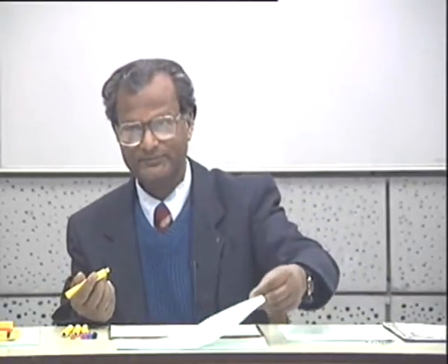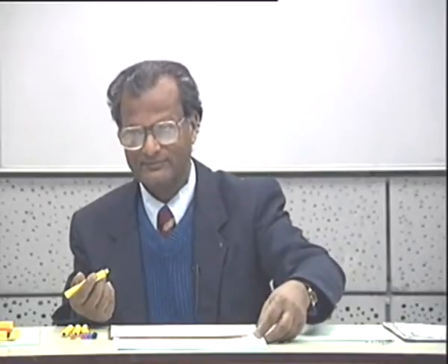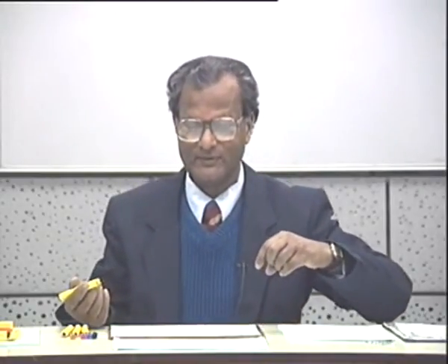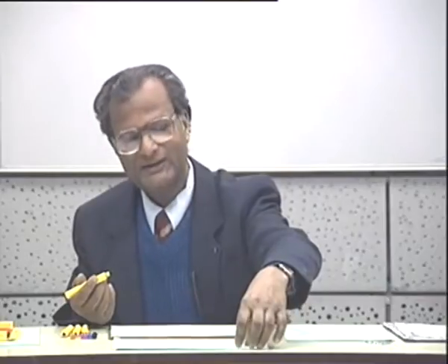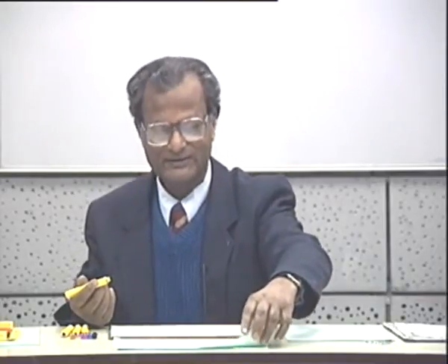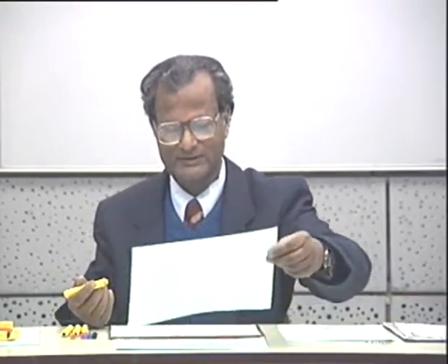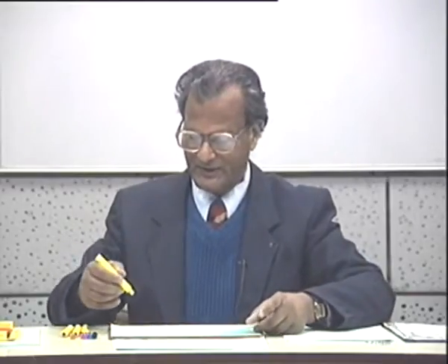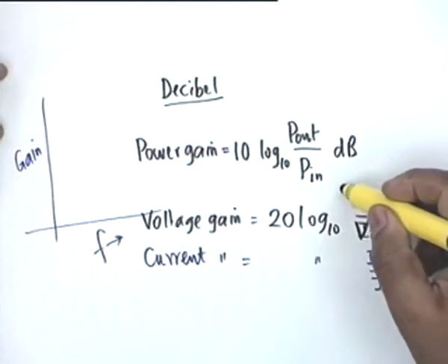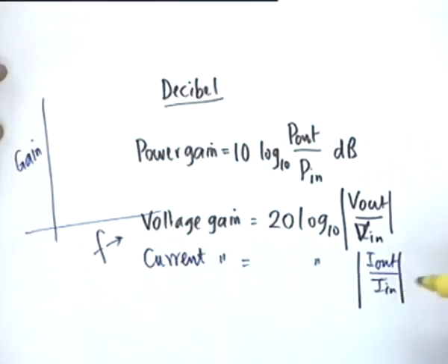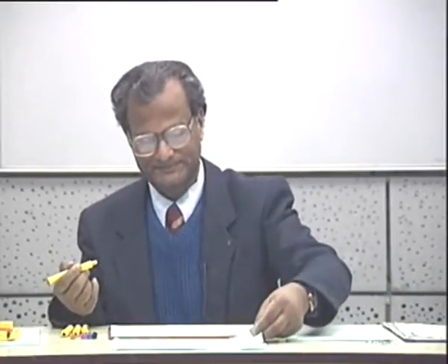Okay. So in this decibel case, this ratio is the phasor ratio? This ratio is the magnitude ratio. Okay, that's a good question. The gain that we express here is usually the magnitude ratio, not a phasor. Decibel with a phasor ratio doesn't mean anything. Decibel is always with reference to the magnitude.